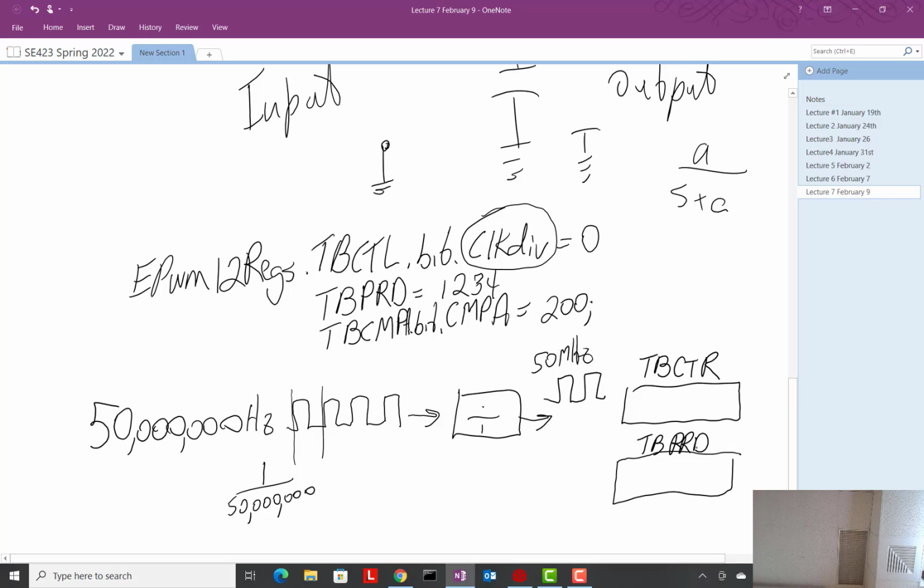So what did I do up here? I set the period to just some random number, 1, 2, 3, 4. So what happens? TB counter is 0. Then 1 over 50 million seconds later, it goes to 1. The next 1 over 50 million, 2, 3.